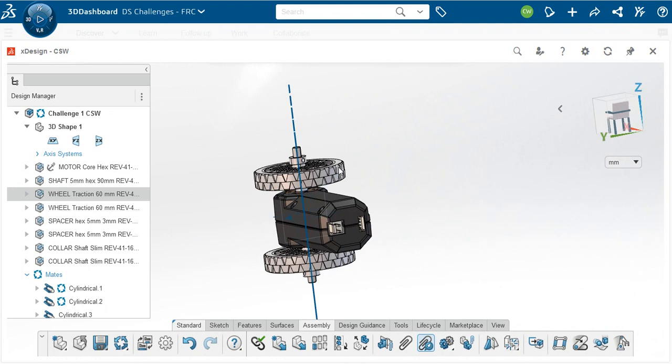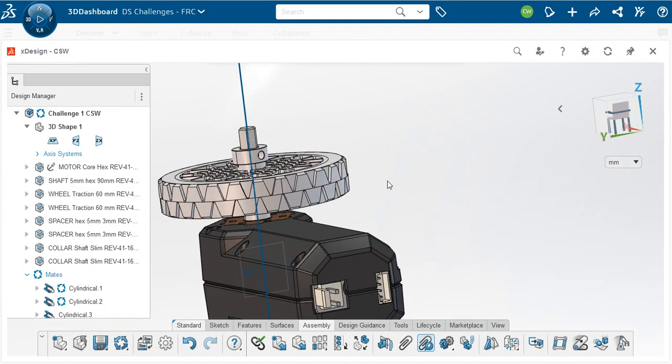It's right here. It sits in this hole. And that set screw will screw in and it will press against this face of the shaft to keep the collar from moving on the shaft. So what we need to do is something like a set screw to make sure that the shaft is not moving inside this collar.